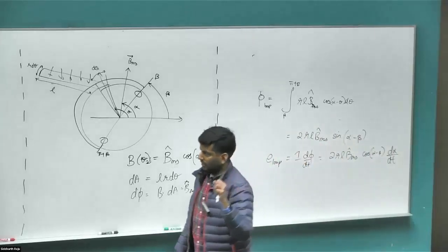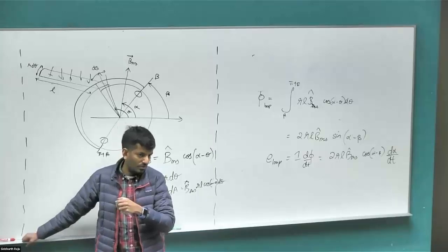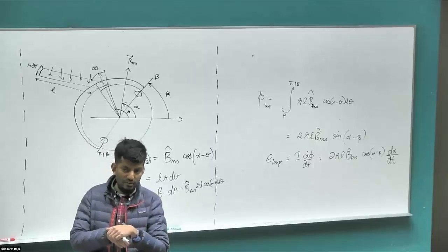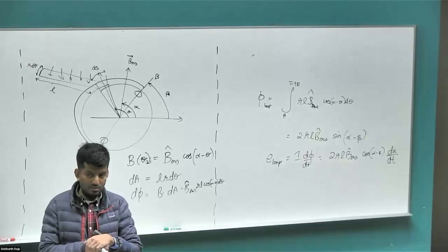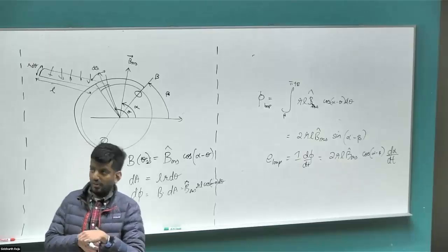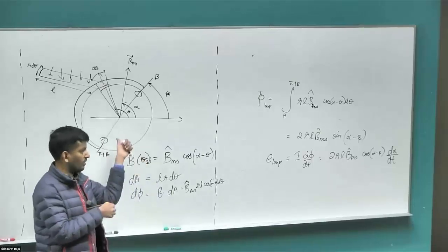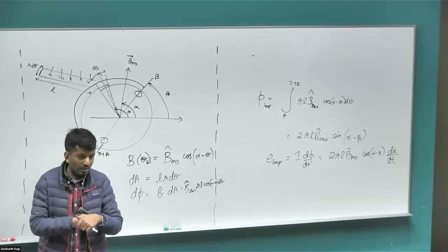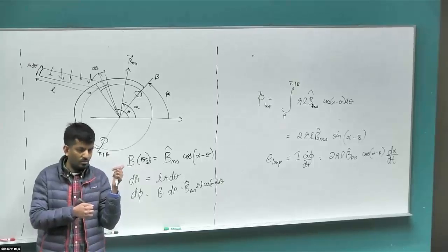What is d alpha by dt? What does it come out to? Mechanical frequency? Or no, the electrical frequency? Why electrical? Because the EMF frequency has to match the electrical frequency. Right? But what is alpha in the diagram? What is alpha pointing to in the diagram there? Basically the location of the stator space vector. Right? And what speed does the space vector rotate at? It has to be the electrical speed.